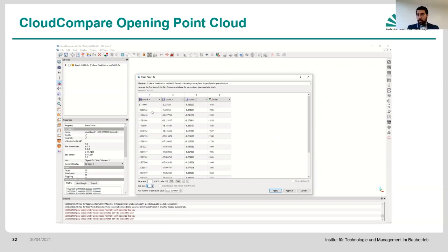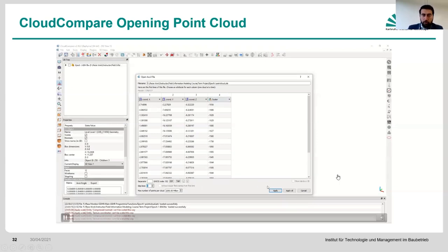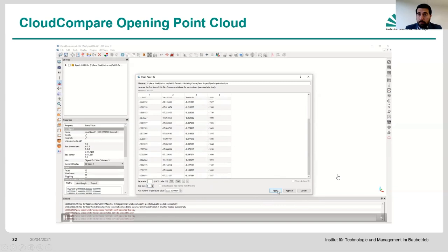If you want to open your PTS format in MATLAB, the only thing that you need to do is save that particular function that I've put there in your project, in wherever your MATLAB is in that particular area. And then you need that particular epoch that you want to open up. And then you put that function there, which I'm going to explain, and it would read the whole file. But in this, it's a good practice to remove that. If you don't remove it, it would still read it. There's no problem. But it's good for you to know that you can have that flexibility if you really choose to.